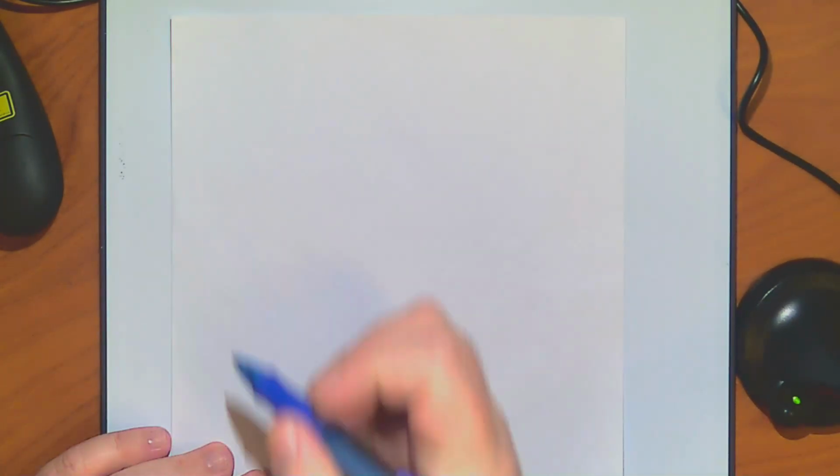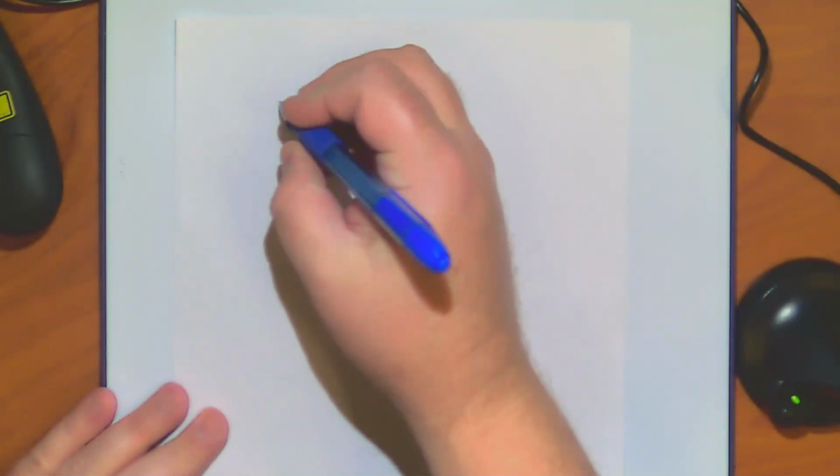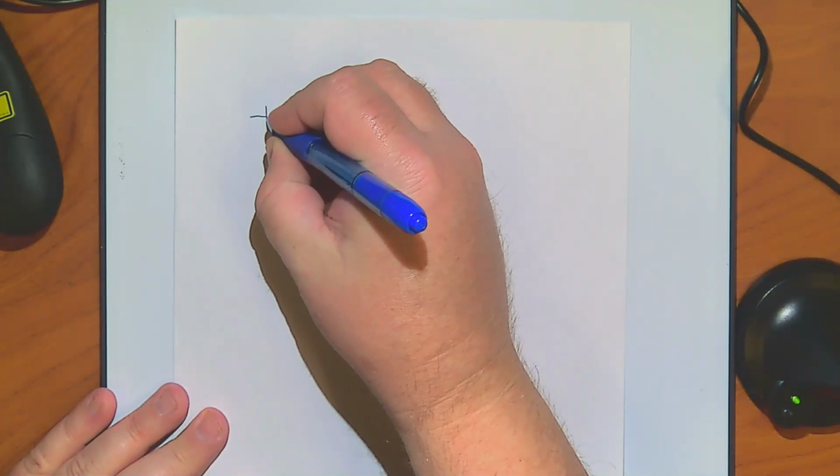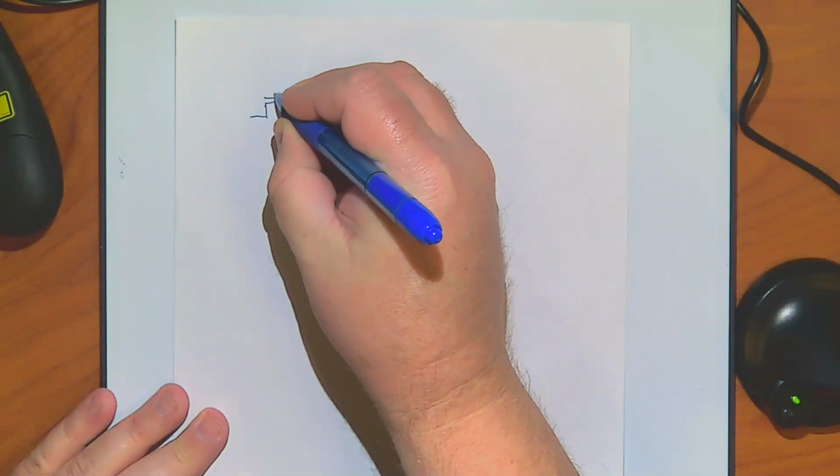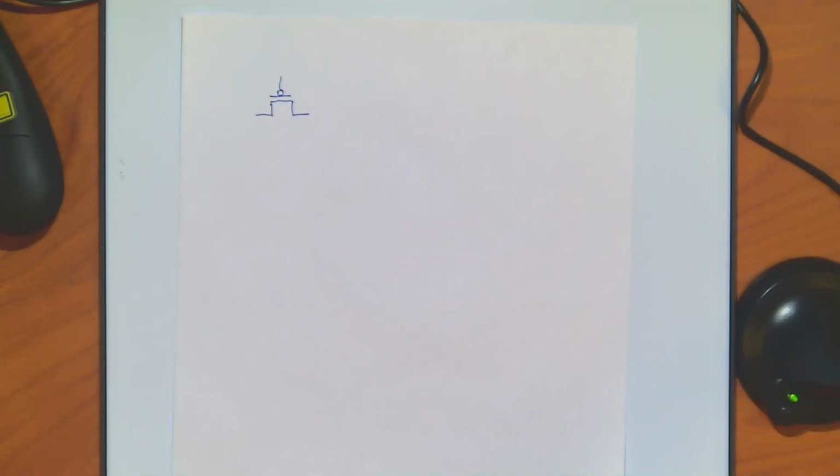All right. So let's start off with transmission gates. Think for a sec. What type of MOS is this? Is this N or P? P. Yeah, this is a PMOS. Remember two ways you can think of this. The technical reason is, what is the actual channel you have to create to connect them up? And it's a P channel. You have to induce it, which means you have to put minus charge on the other side of the capacitor to induce the positive charges. Okay?